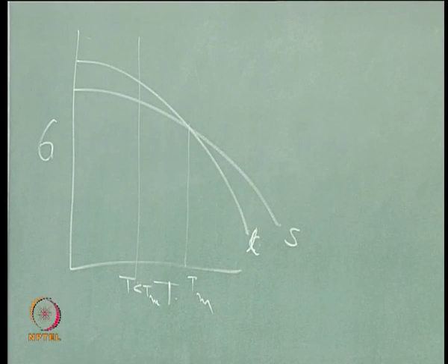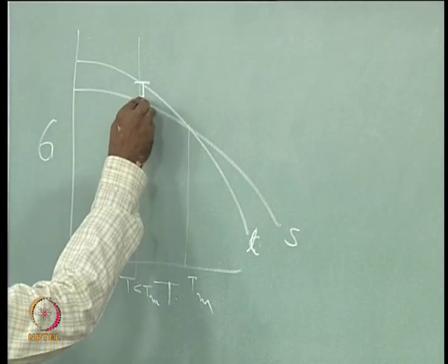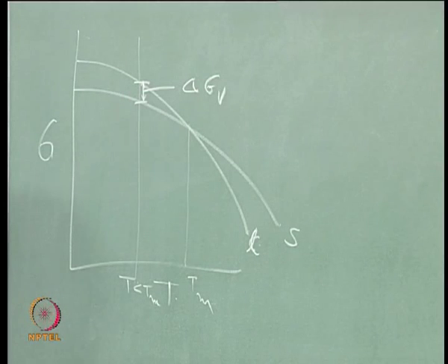Am I right? And this difference in the free energy between the liquid and solid, which is what we call delta G V, that is our delta G V, and that is what drives the liquid to become a solid. And the higher the undercooling, usually this is higher, as you can see from that curve itself.